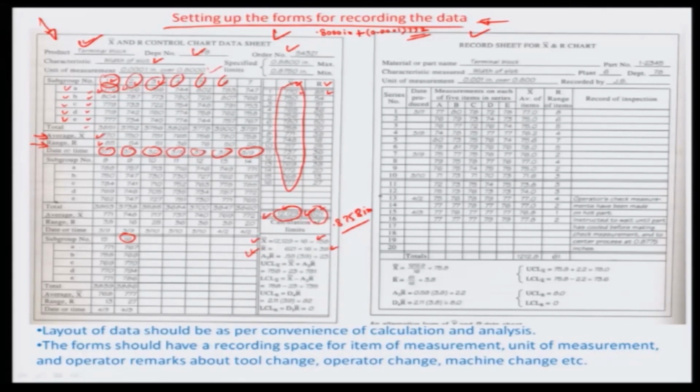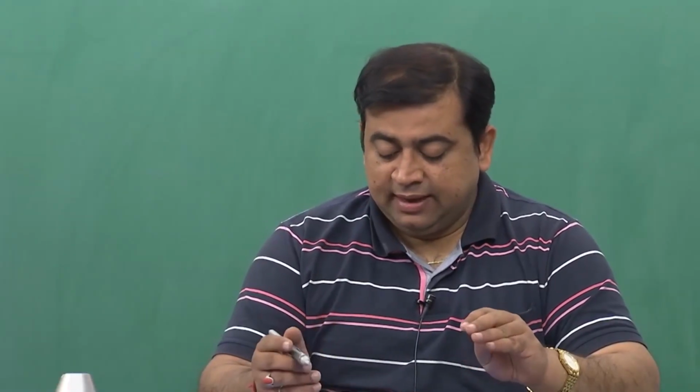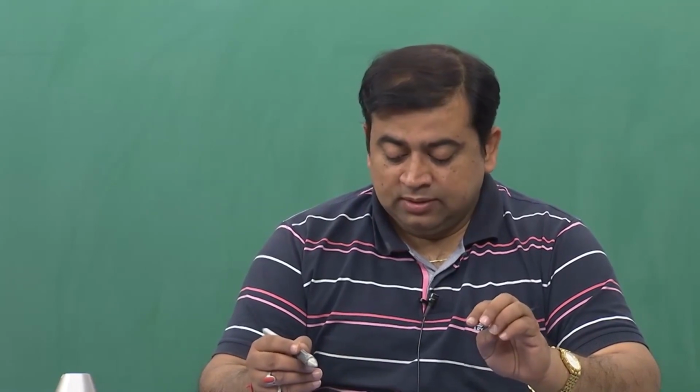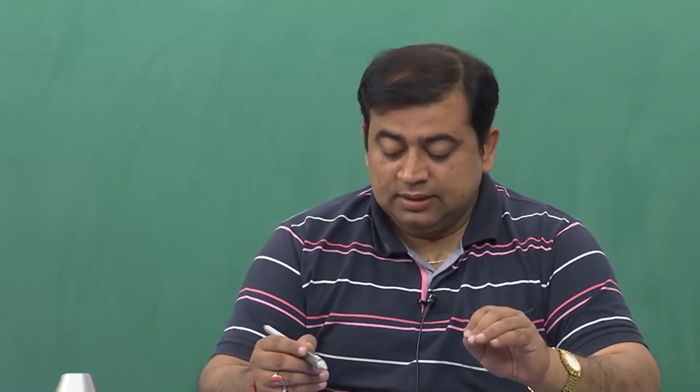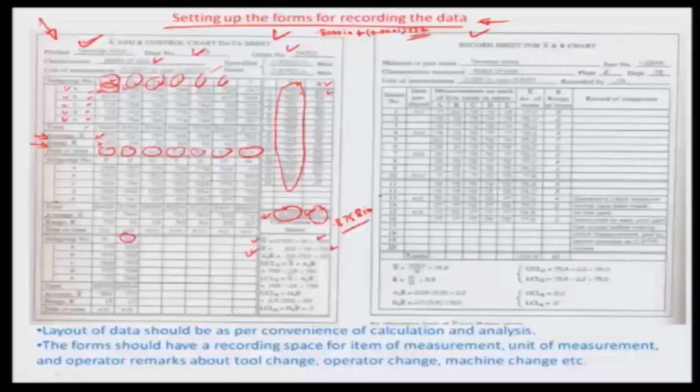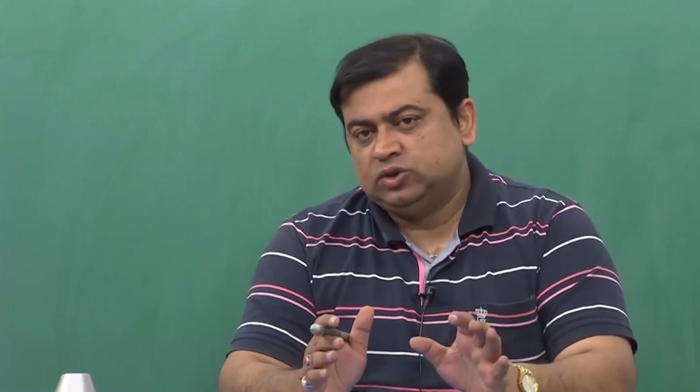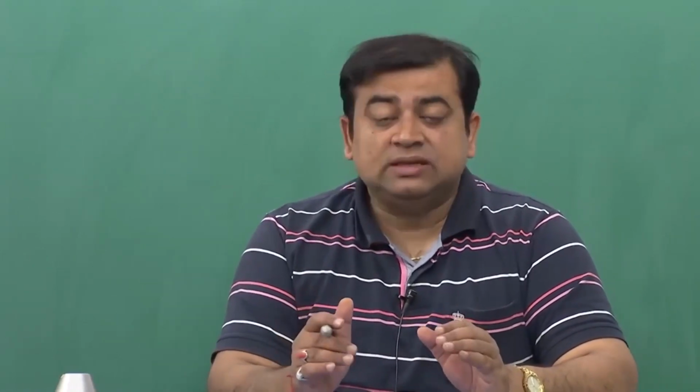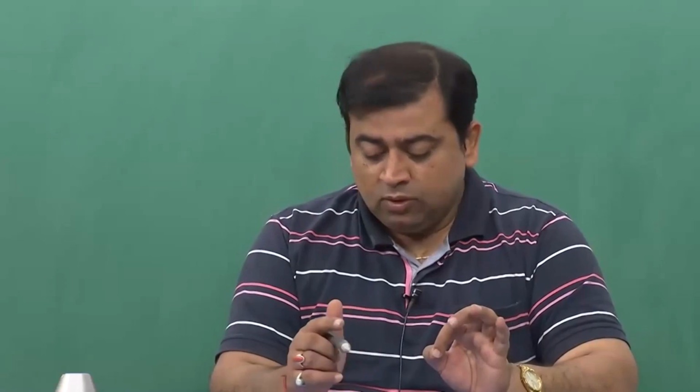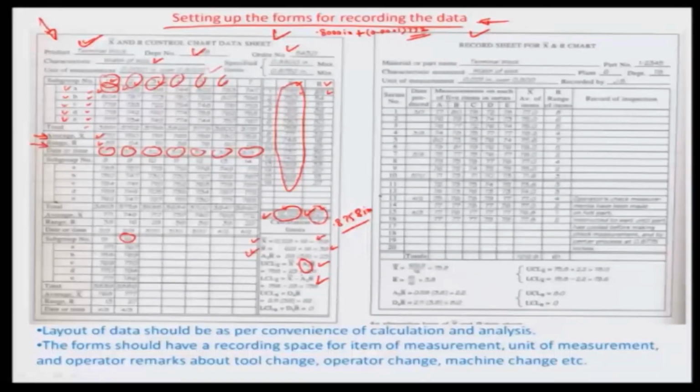Having said that, now you have to go back to the Shewhart control method, where they talk about the factors which are associated with plotting the X chart. Typically there are 2 control limits that have to be set. One is the upper control limit of X, another is the lower control limit of X, and I am going to share that table with you a little later. But as of now, just think of it in this manner, that based on the subgroup size that you have obtained, you can select the A2 value and the A3 value.